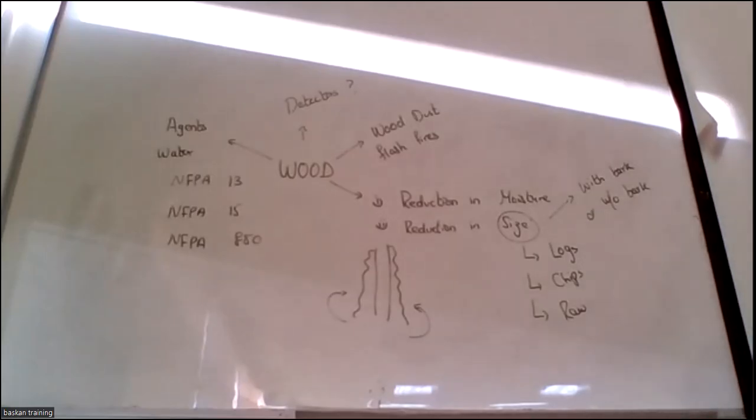Eventually, civil defense reviewed the drawings and changed them, sending them back to the consultant to install heat detectors. So one of the detectors that we tend to use in wood areas, since we don't have another option, is heat detectors. The other option can be flame detectors, but when we say flame detectors, the false alarm ratio is very high, again the same as smoke detectors.